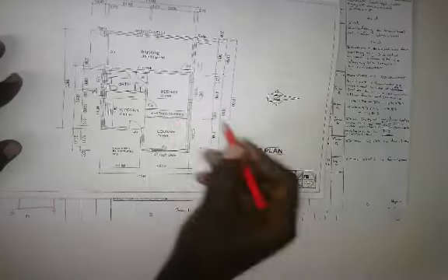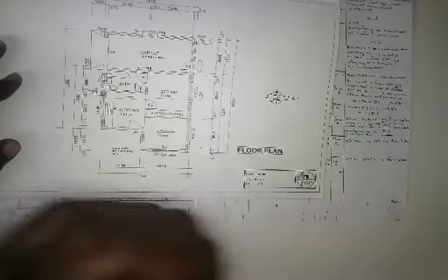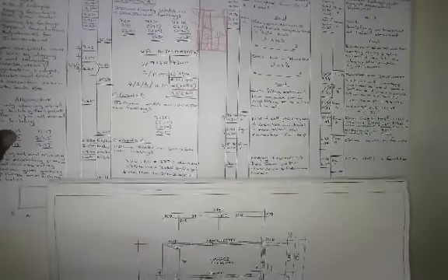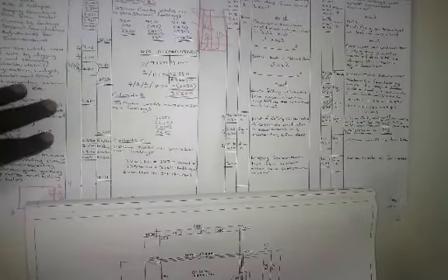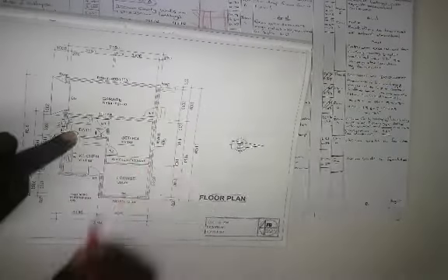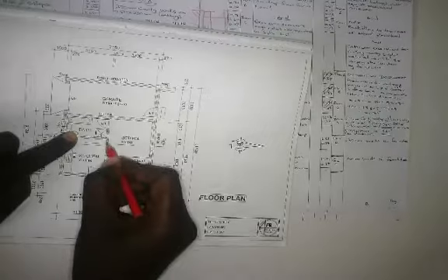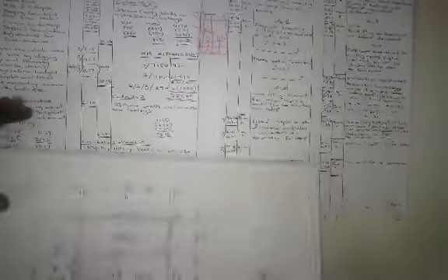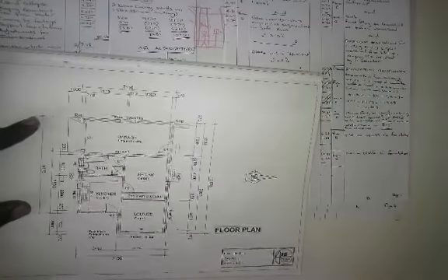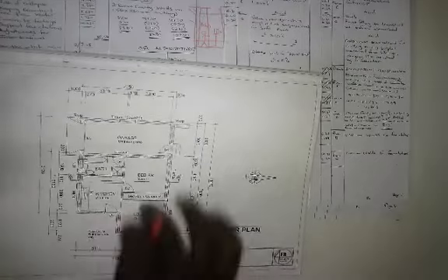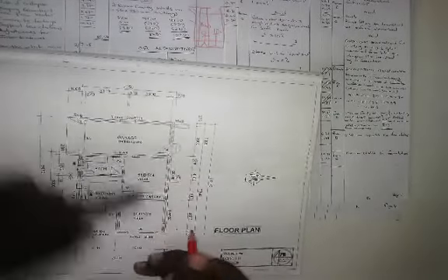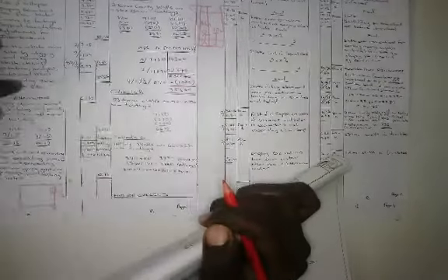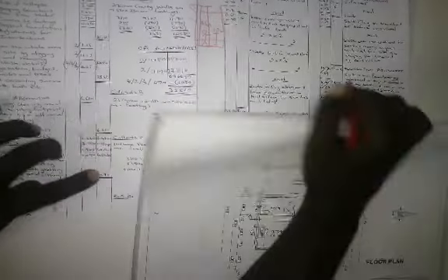Okay. Then you go to your 110 walls. In your 110 walls, it's also just very simple. You just take the dimensions. You identify a dimension, write it down. So let's first go for your 3.22, which is your bath and kitchen wall. So here's your bath and kitchen wall. So it's just 3.11 plus the 110. That gives you 3.22. So you identify, you write it down, you color in that part that you've already done, and so on with all the walls.